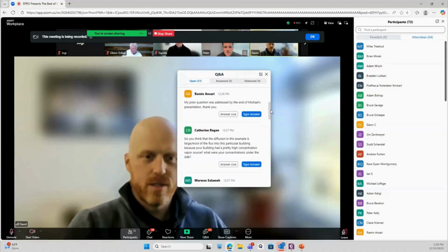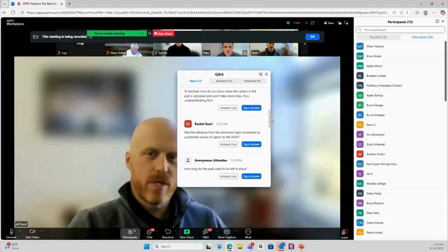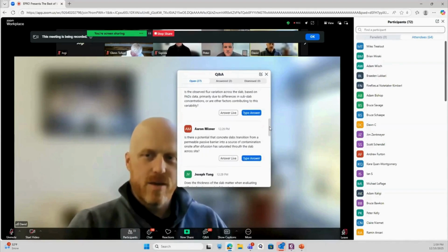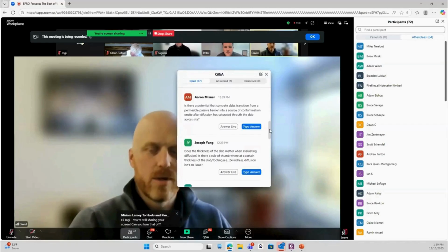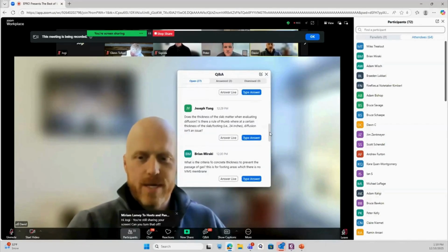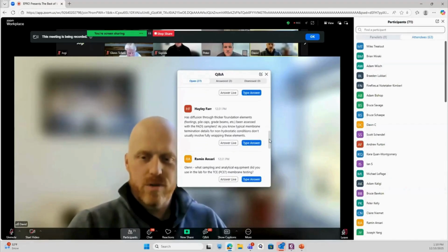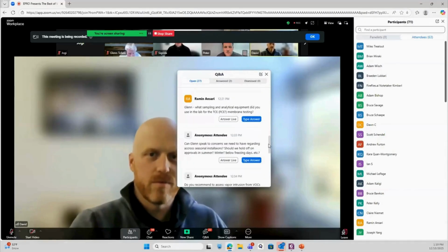It creates a good vacuum influence. In some situations where we did have problem areas where we didn't get great readings, in each of those cases that I can think of, it was resolved by either improving the test port, removing water from it, or installing another test port just nearby. And it seems to be that was typically an issue. So none of these that we had to end up putting in an additional riser. I can't think of one project historically that we've done where we did have to recommend to put in additional risers to address areas that couldn't be influenced.